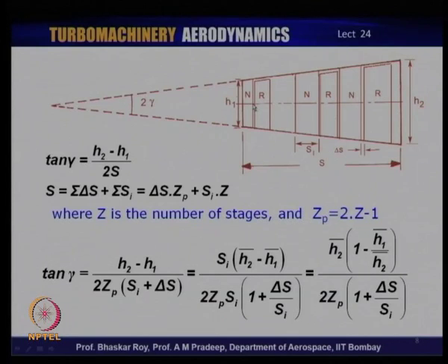You also need to take a call on the axial velocity, and then you apply the continuity condition, and at each of these stations you have your annulus area, which then, knowing what the mean or median radius or median diameter is, you can use to calculate the annulus height. So, that is how you get the height of the blades from simple continuity condition application.